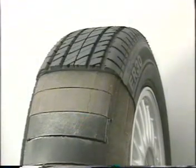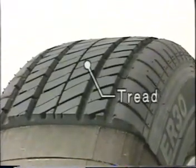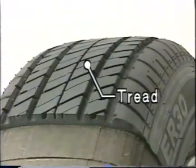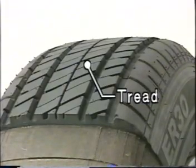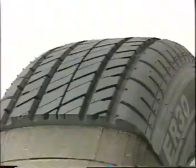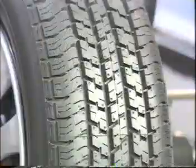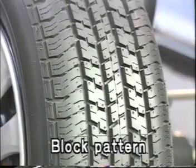The tread comes into direct contact with the road surface and transmits the driving and braking forces to the road. It protects the carcass from wear and shocks caused by the road surface. A wide variety of tread patterns are molded on the surface to transmit the forces effectively to the road.